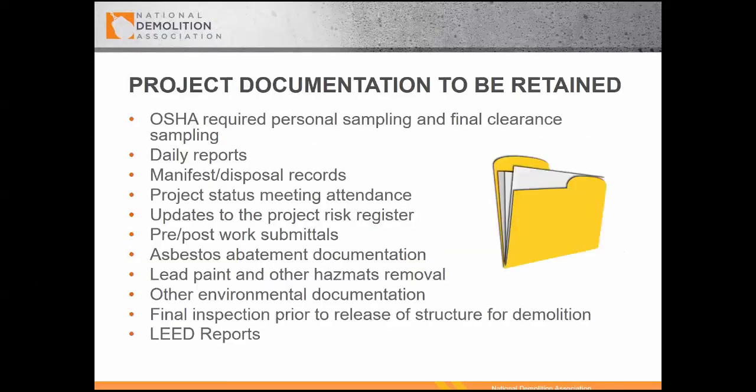Project documentation to be retained. Obviously, personal sampling, we had just talked about how important that is, daily reports, manifest disposal records, project status, meeting attendance. I would have all your workers sign the daily safety meeting, just so you have a record that they've attended that. Updates to the risk register. We didn't really talk about the risk register in this module, but we will in the risk management class.